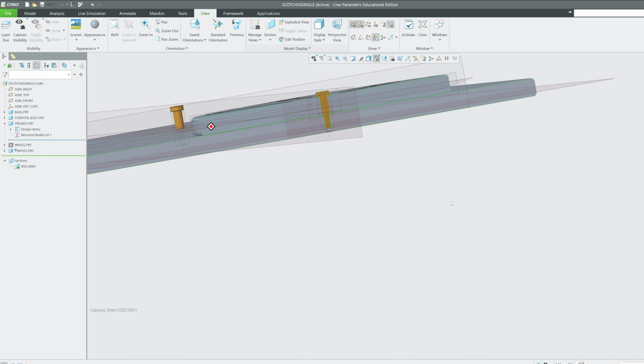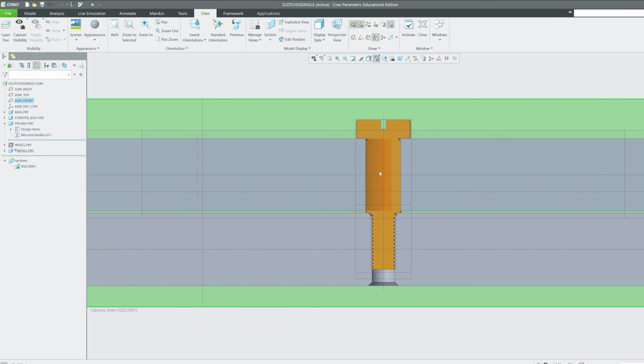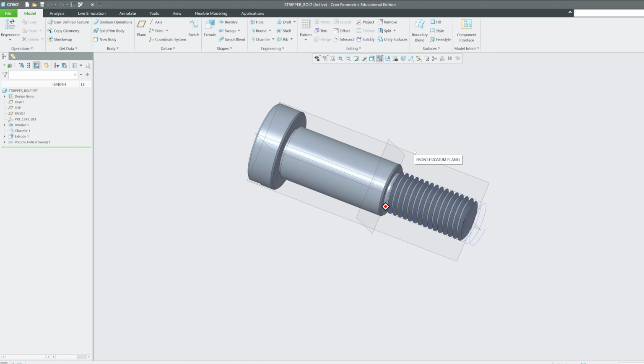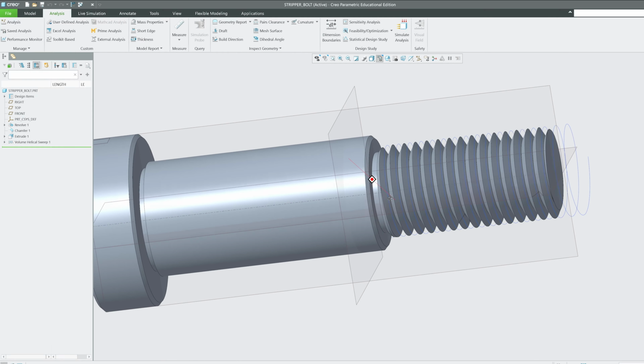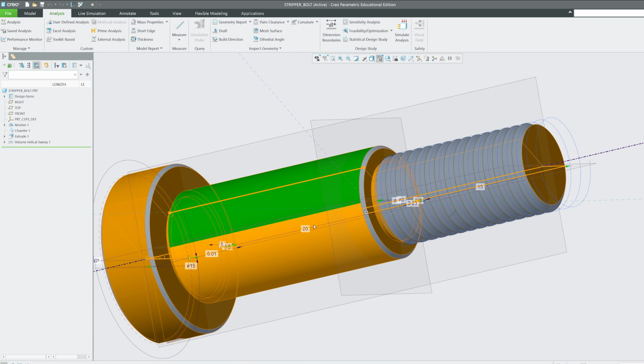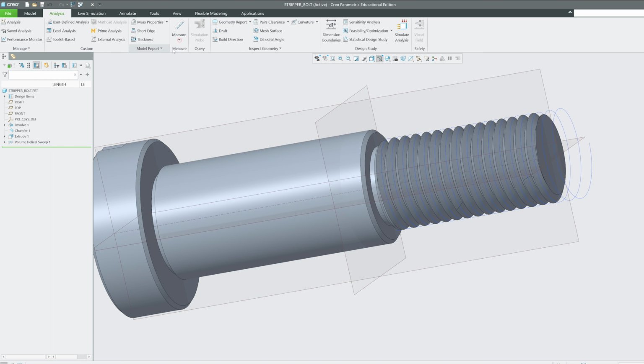All right, so if now I see it from this side, you will see that there is a gap upside also a little bit, and then in the bottom also. I do not remember actually how much I provided, but you see how much it was actually. So let's quickly measure this distance from here to here, 20.5. All right, so since we have added this undercut, so that's why. So let's make it actually 19.5. Control Z. Now it will be 20.